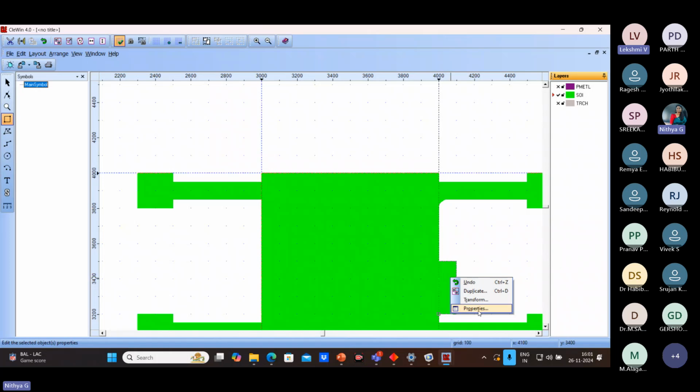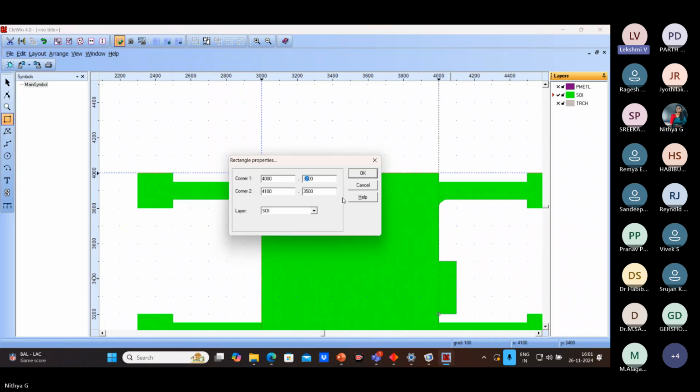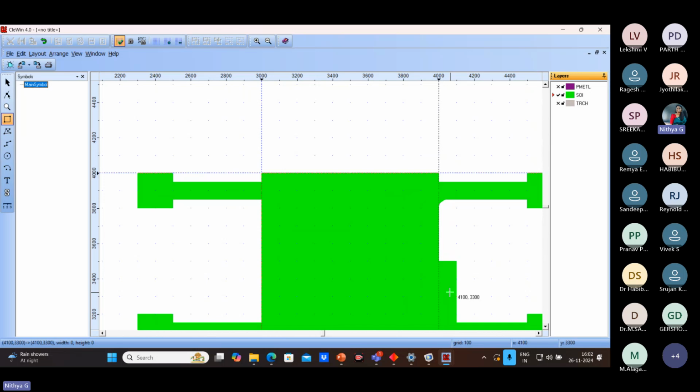Hello, ma'am. Yes. Is it possible to export the two-dimensional geometry from COMSOL? No, it's not possible because it is completely a layer information, Uma. So the input is only the layer and the structure. So in this tool it is not possible, whereas, as I mentioned in the beginning, in Coventorware or IntelliSuite, it is possible. There you directly take the layers and simulate. That is a kind of similar approach to the fabricated device, whereas this is only creation of the mask.